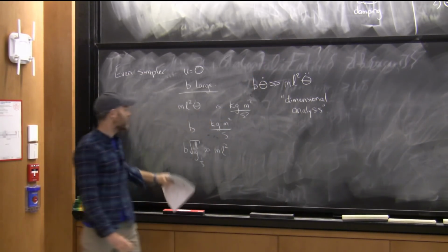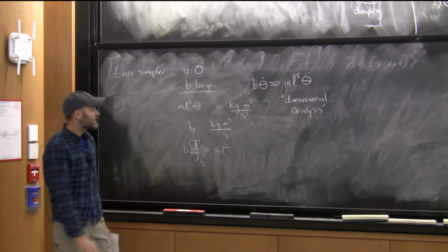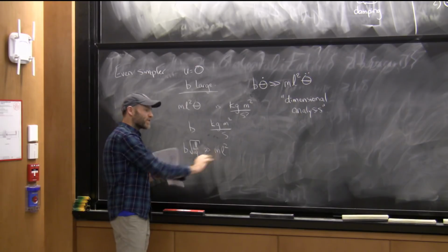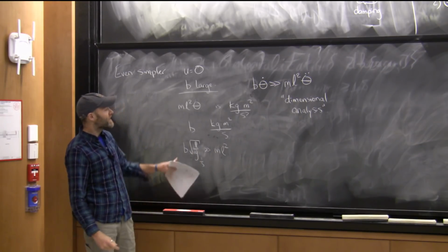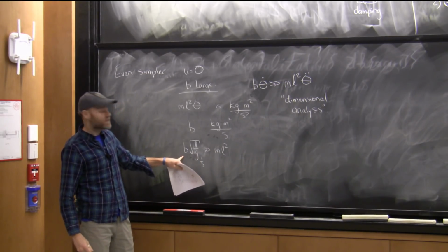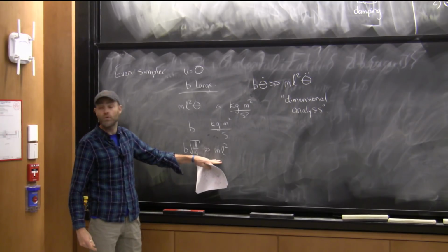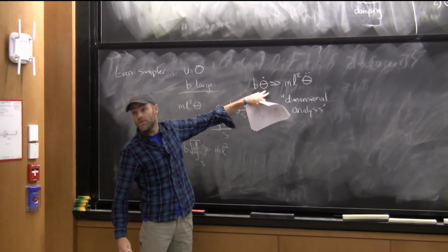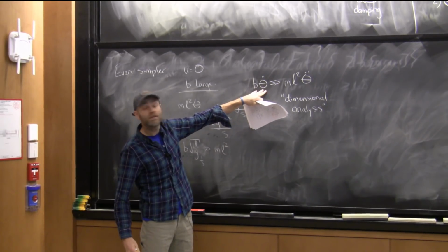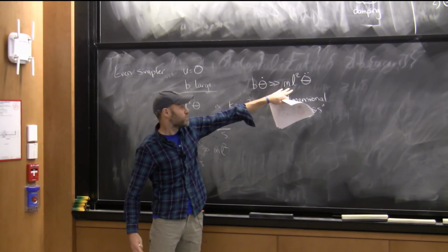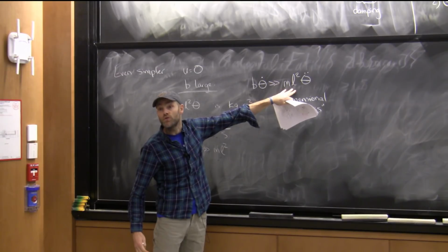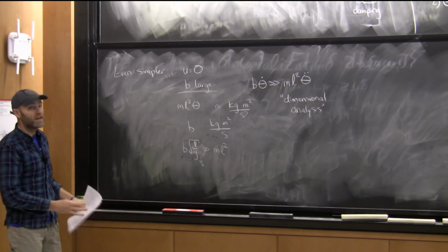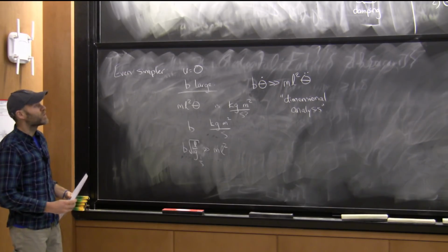But somehow, dynamicists are kind of like, meh, put a characteristic time constant, you got the units the same, now you can make a statement, and that's going to allow me to simplify everything. If this relationship is true, that implies that my terms in that equation, B theta dot, dominate my terms that are due to acceleration. And that's going to allow me to think about a simpler form of the equations, which is a first order system.